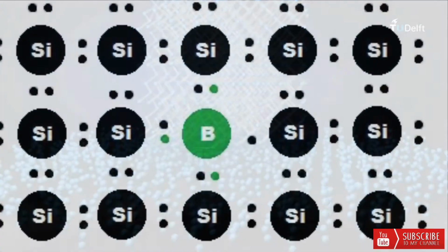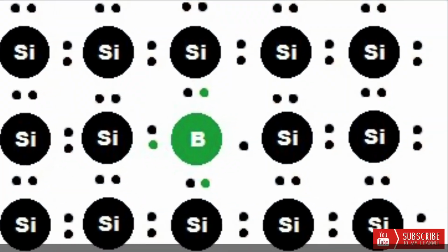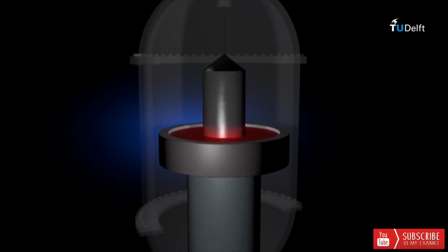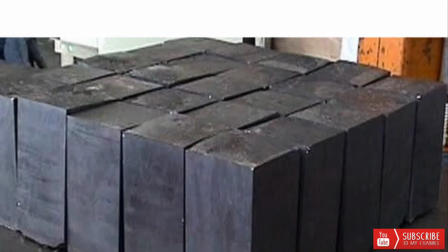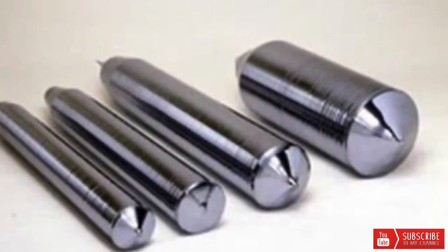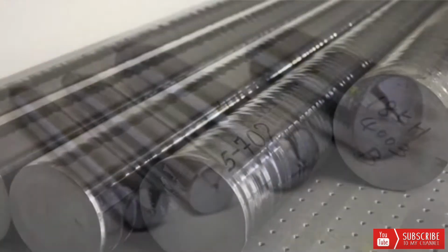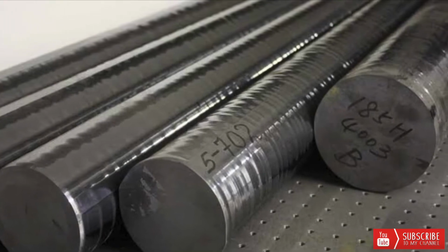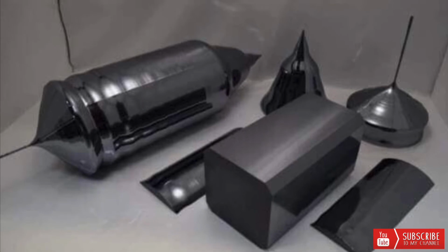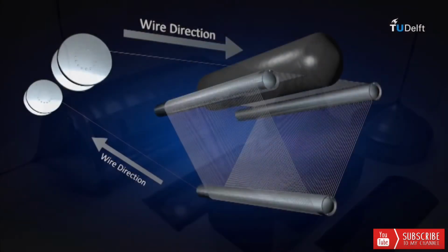During the ingot making, boron is added, which gives the silicon positive electrical polarity. This can be termed as p-type doping. Polycrystalline ingots are usually in square shape, whereas monocrystalline ingots are cylindrical because of the production method. After the ingot has cooled down, grinding and polishing are being performed, leaving the ingot with flat sides.